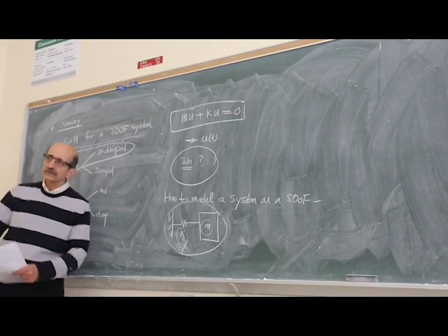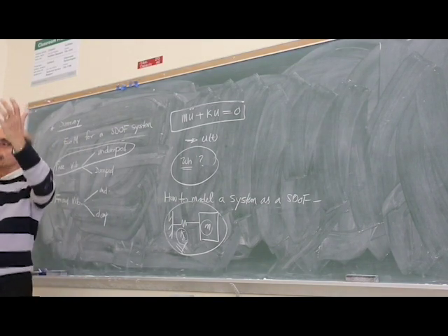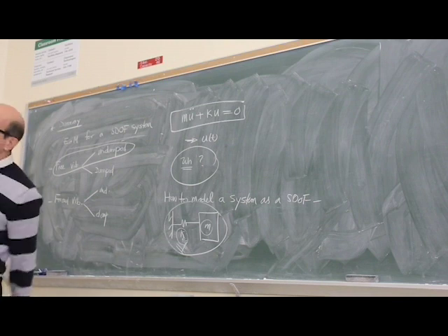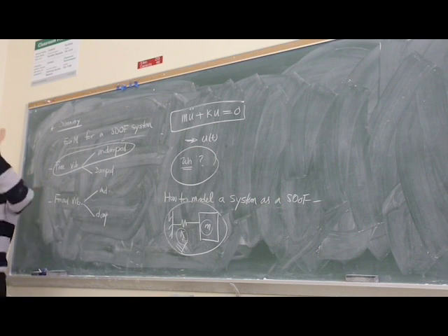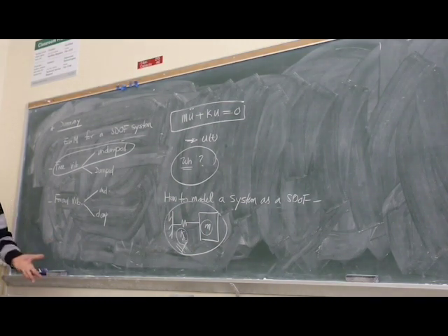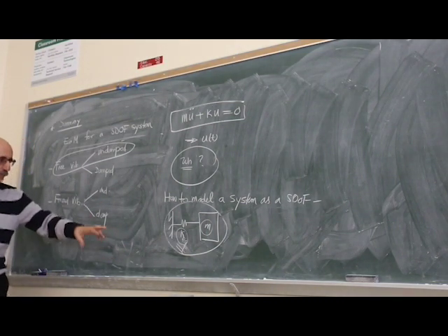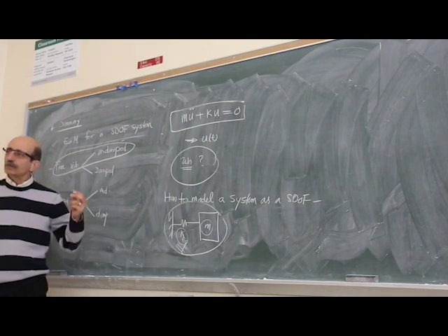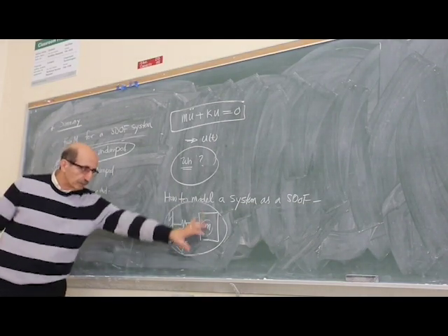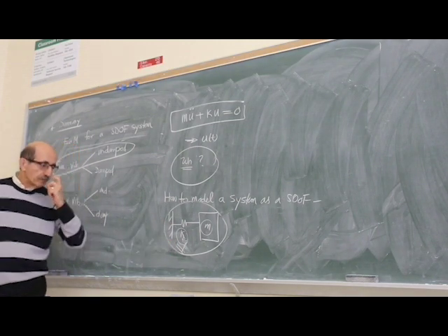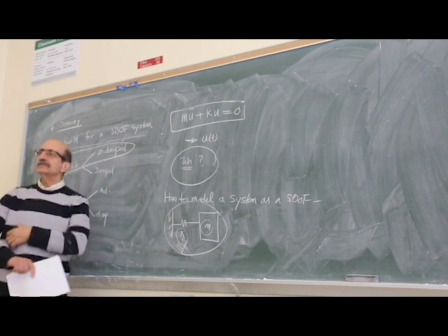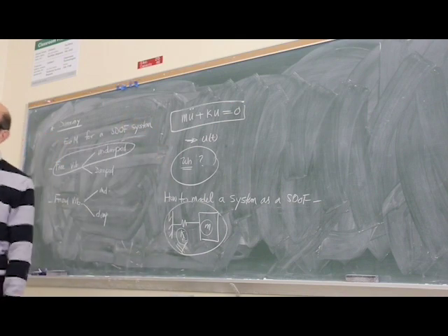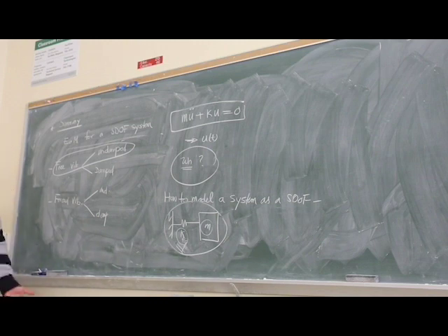What does that mean? A system, let's look at it, a building, consists of floors, columns. These columns are what resist the motion of the floors, right? They resist that. So they're the ones that represent the stiffness. But you have so many of them. What we are trying to do by developing this model is, is it possible to come up with a single spring that can represent all these stiffness elements? Or in the case of a mechanical system, for that matter.